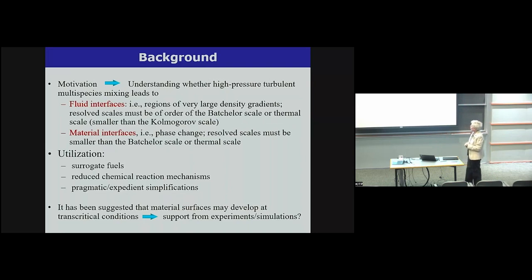Then we're talking about reduced chemical kinetic mechanisms. For hydrocarbon oxidations, these involve, I would say, at least 2,000 species and at least 10,000 reactions. So how are you going to deal with something like that in a simulation? Totally impossible. So people derive reduced reaction mechanisms.